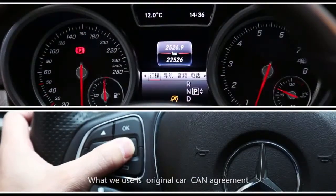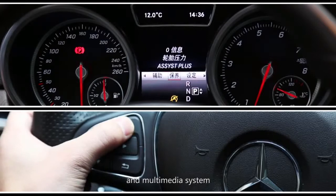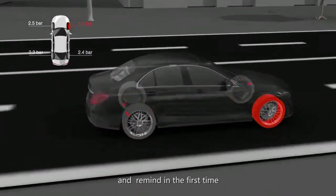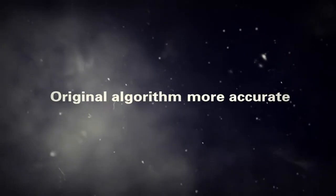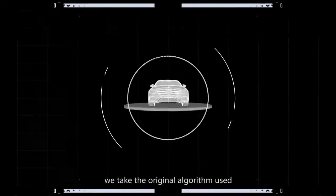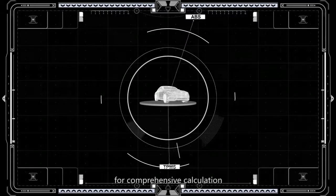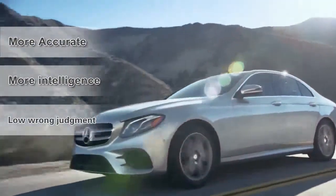What we use is the original car CAN protocol to communicate with the original car dashboard and multimedia system, which allows detecting the tire pressure data at any time and reminding in the first moment when an accident happens. Original algorithm is more accurate. Combined with the original car indirect TPMS, we take the original algorithm used on the original car ABS system data and the tire pressure data for comprehensive calculation, which could be more accurate and more sensitive.